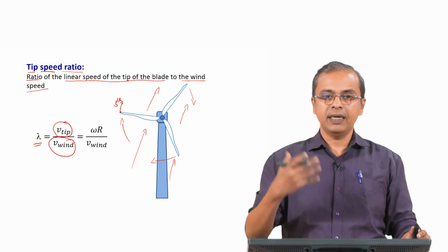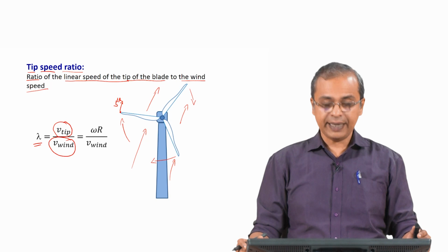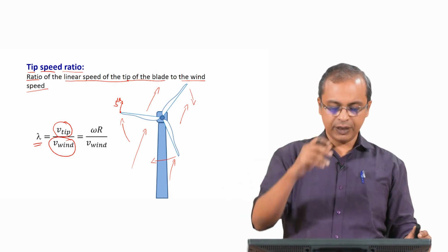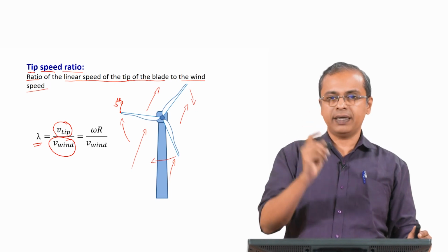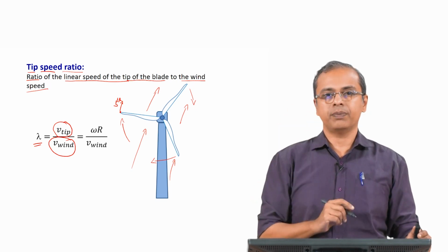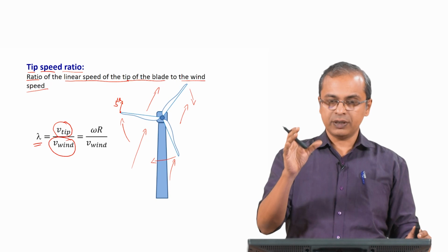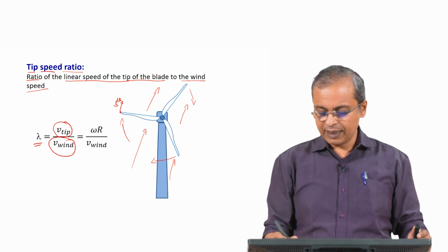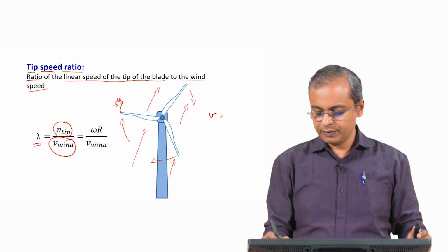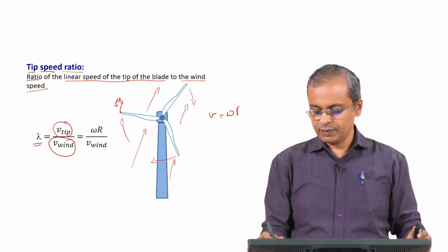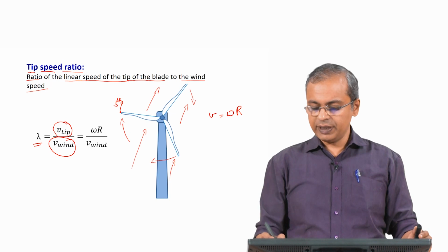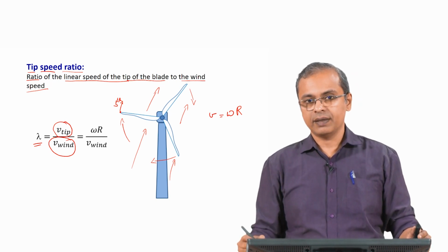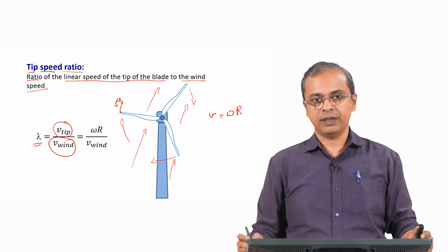Okay. So, this is what we have, and if you look at angular velocity versus RPM of something that is rotating, you look at how many radians per second it is going through in this angular motion, then the linear velocity of any point, as a result of this angular velocity, is simply V equals omega r, where omega is the angular velocity and r is the radius of the point for which we want to know the linear velocity, right.